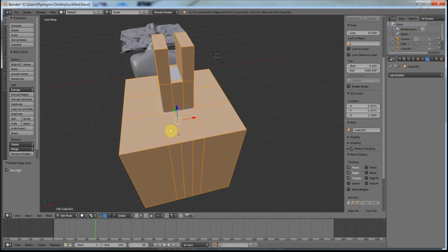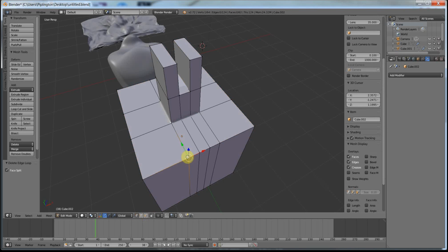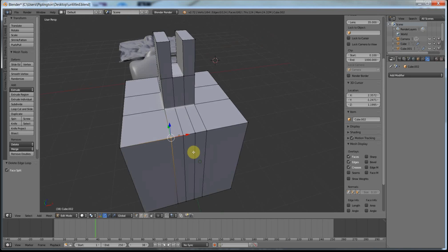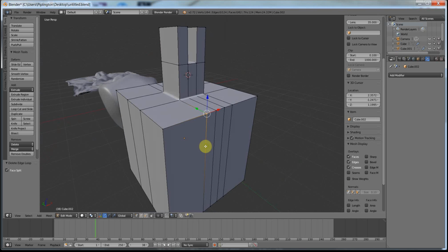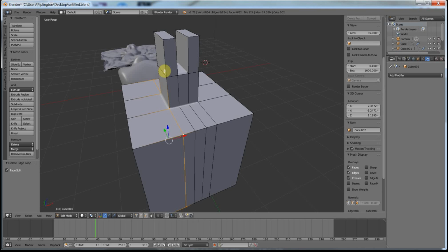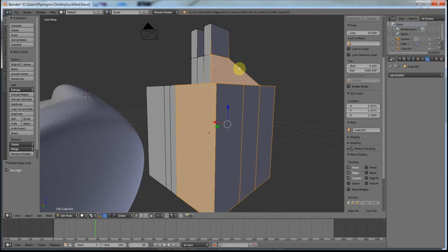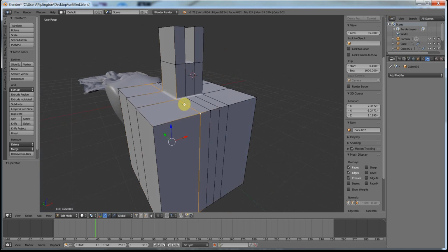And some people might just stop there, but this isn't actually low poly because there are some pointless vertices in there that we don't need. So let's start using the second most important tool. We can use that to select any edge loops, but if we've got a situation like this, I can't select this whole edge loop and delete edge loop because it gets a bit more messy than we'd like it to be. I'm not sure what's happening in there, but it's not quite the right result.